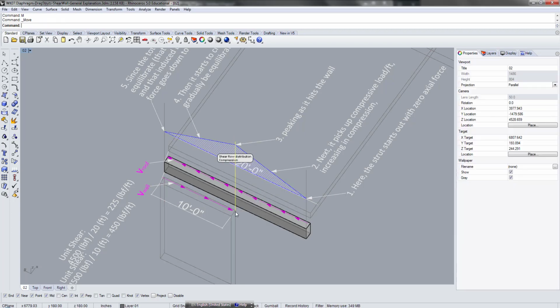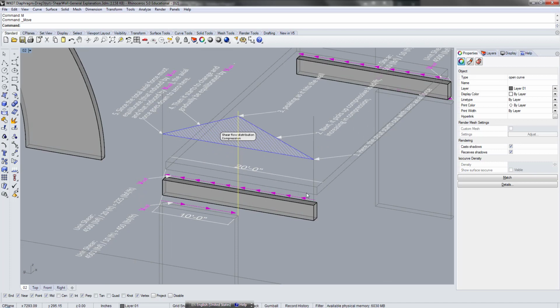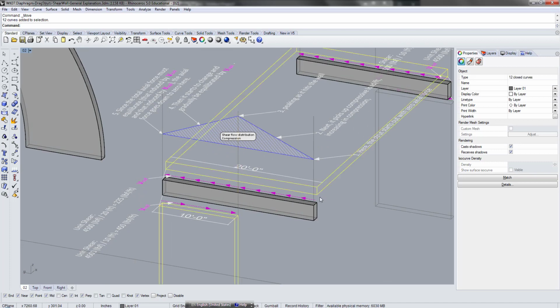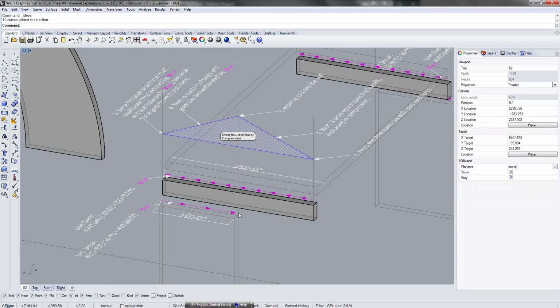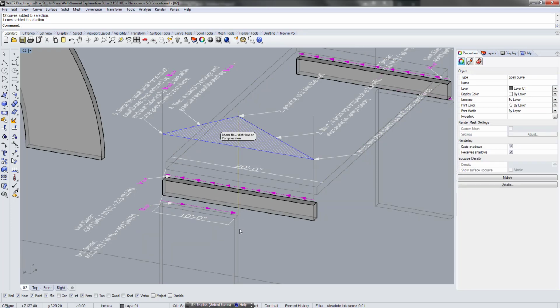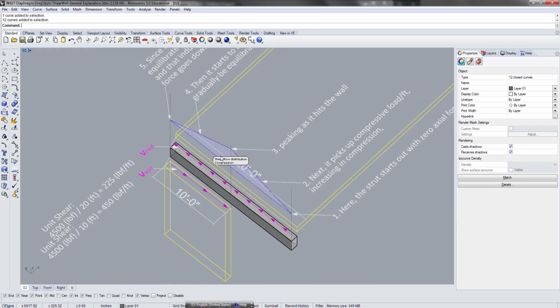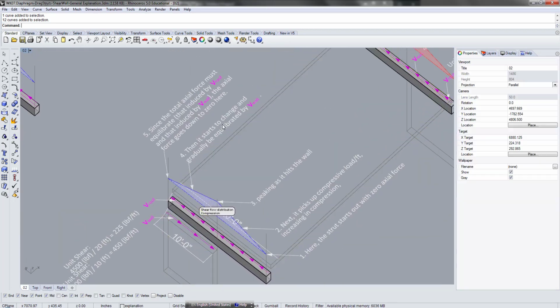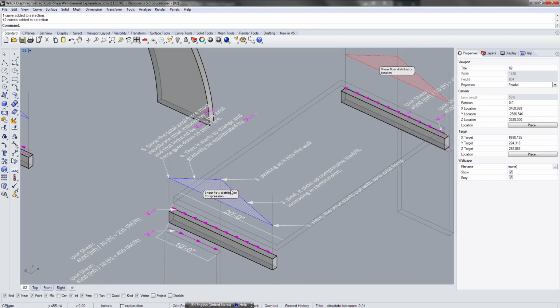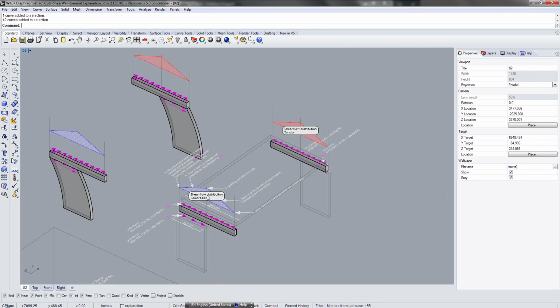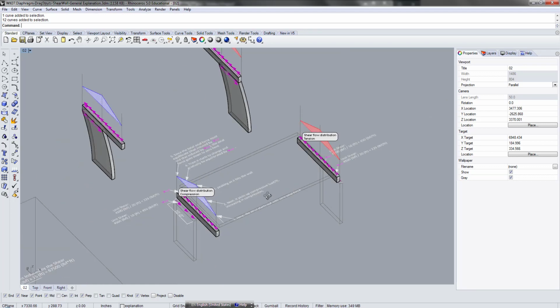Up to here you only have the diaphragm pushing from above, but at this point you start to have this shear wall beneath pushing you in the other direction. So now it starts to change and gradually be equilibrated by the wall, so it starts to decrease, and the total axial force must equilibrate at the end, so it becomes 0 again at the end.